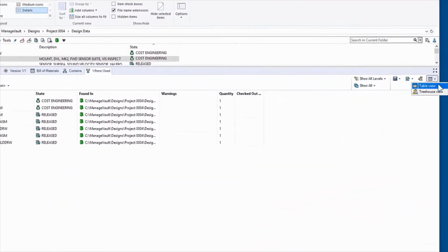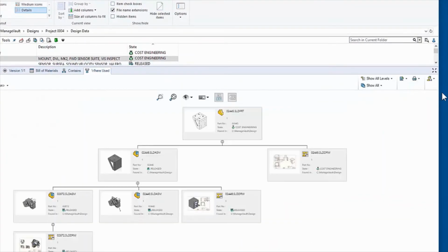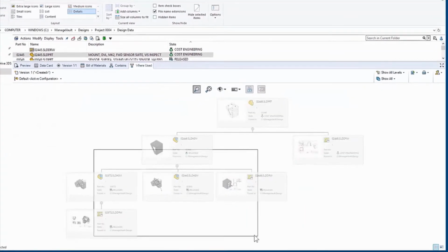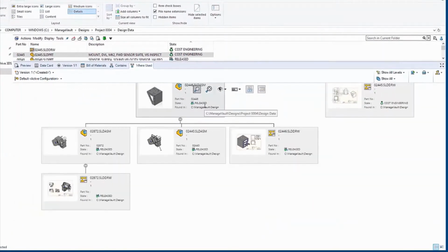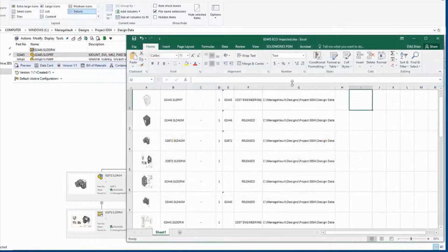Fast forwarding, I have redesigned the bracket to use aluminum plates. Converting this into a weldment creates cut list items, and in 2021, these are fully supported in PDM calculated bills of materials. Even excluding from cut list is now taken into account.